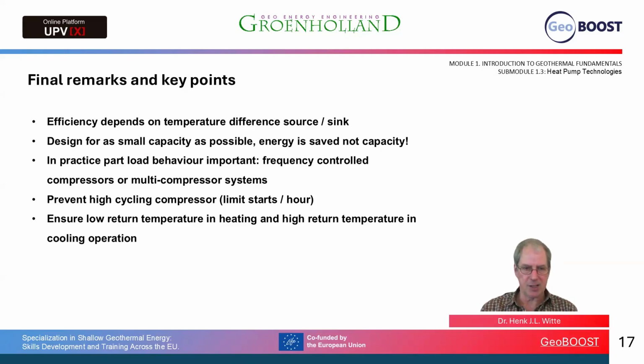If the compressor size is too big for the load, it will start-stop very often, and this will result in low efficiency, but also it will wear out the compressor and cause faults. And finally, on the building side, what's very important is to ensure a low return temperature in heating and a high return temperature in cooling, so that the heat pump system can heat the fluid and cool the fluid in an efficient way.